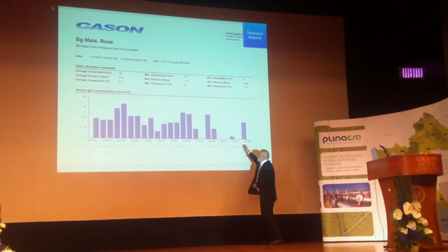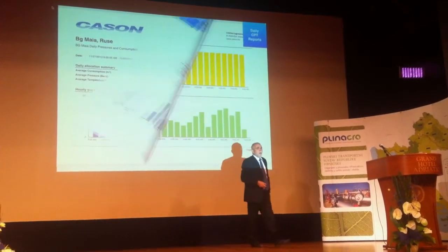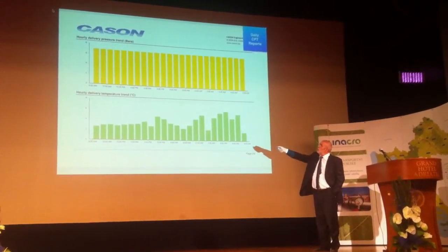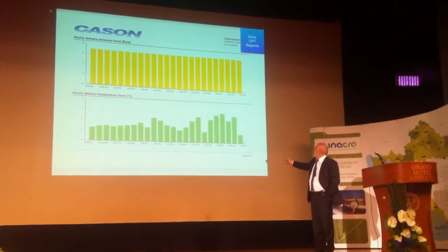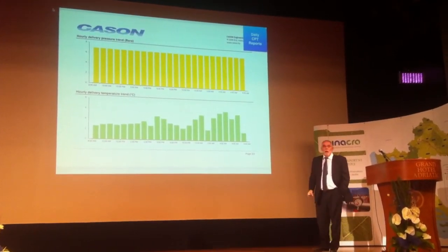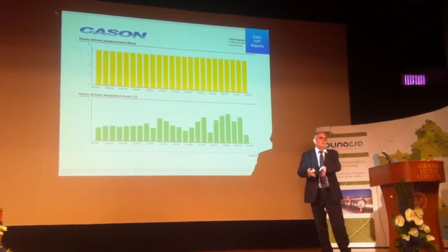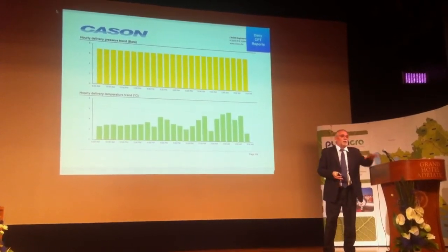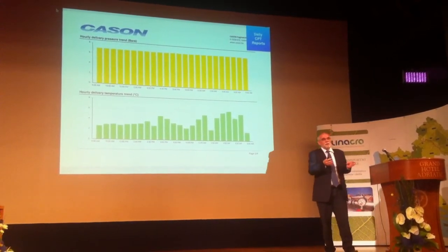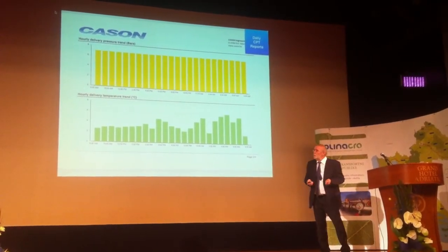This is a station in Bulgaria. You can see here the consumption of that given consumer. In the same report, we document the pressures, and you can see it was nice and stable, and we document the gas temperature, which was quite hectic, but it was quite cold at the time. If you have this document stored in your file server for every station, for every day, then you're on the safe side against your customers, or against your consumers, and even against the Industrial Safety Institute.